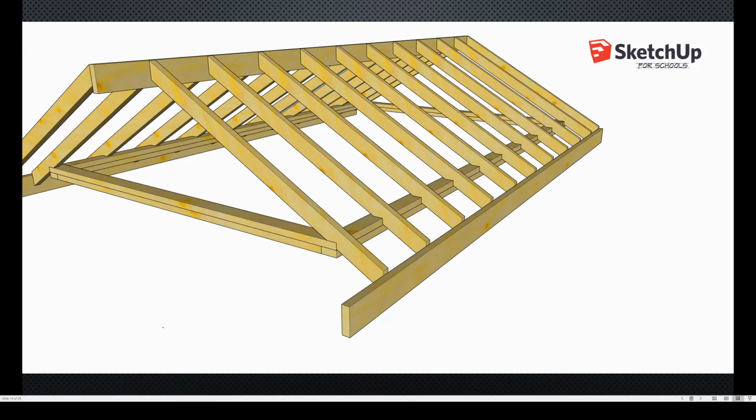In the middle, and this is actually just a view of our roof with the fascia rafter removed, there's nothing holding those rafters from pushing outward on the wall and spreading out. So we could add rafter ties like this. They're nailed into each rafter at the end of the rafter tie, and that will stop them from spreading out.